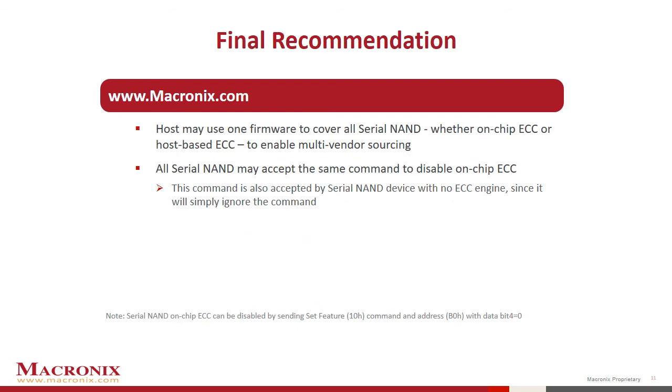Before I conclude this presentation, there is one suggestion I would like to make. We feel we are in the early stages of a new trend, that is, moving from serial NAND with on-chip ECC to serial NAND with host-based ECC. In order to support multiple serial NAND devices from different vendors, we recommend that the MCU or SoC disable serial NAND's internal ECC in the initial bootloader and directly process the error correction via the host ECC engine. This way, it can use serial NAND from multiple vendors with minimal effort.